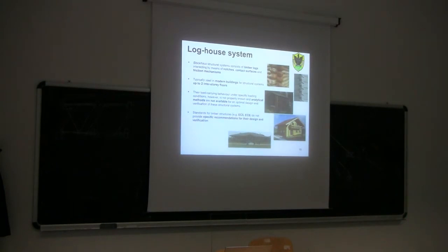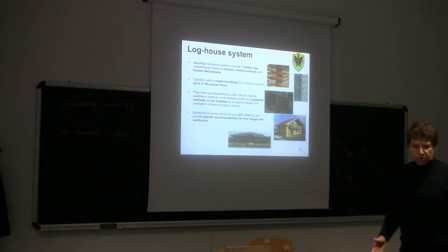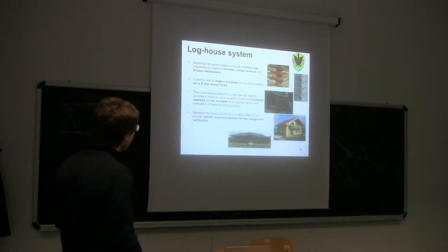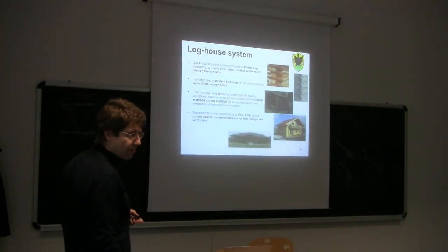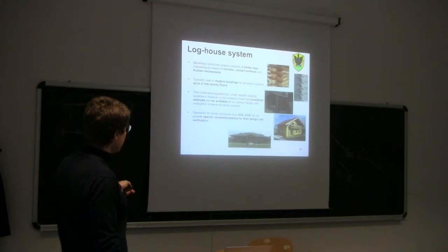In this case, as you can see, it's very important to provide a connection between the perpendicular walls. So the perpendicular walls are connected to each other by cutting some notches into the logs and by basically crossing the logs together. We have different kinds of details for the notches, as you can see.